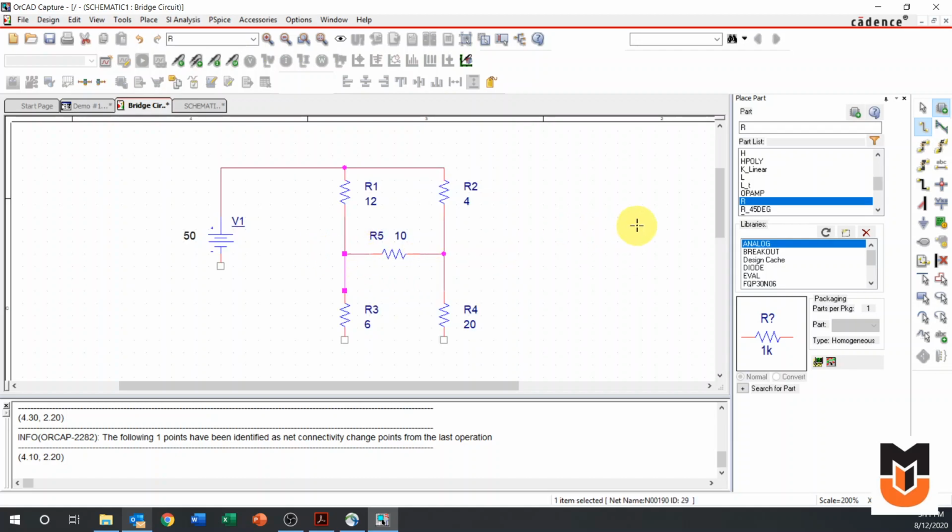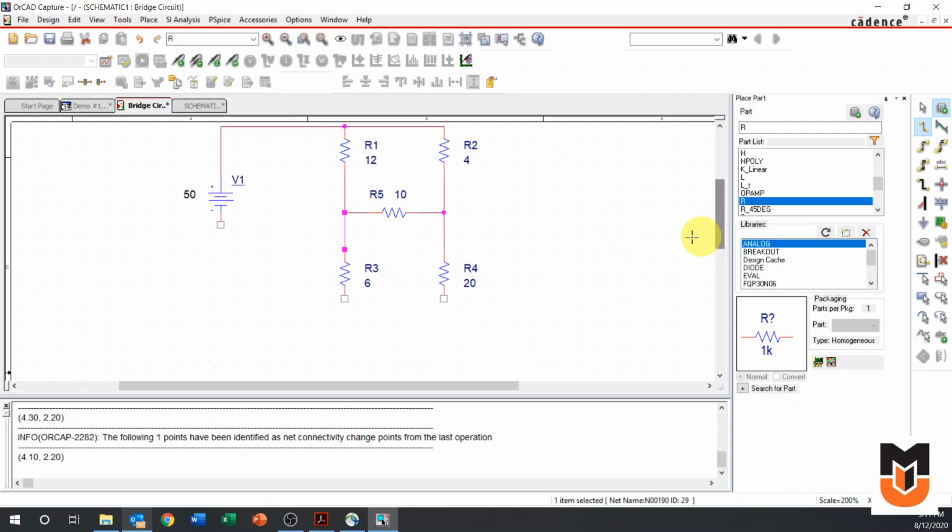So let's say maybe for whatever reason, I'm just going to scroll down a hair here. For whatever reason, I don't want this wire to come straight over and up. Maybe I want to give myself a little more space and go down. So I can first come down with my wire, and then I can left click to set my bend point as being right there, and it won't auto adjust it. And then it's going to auto adjust as I come up here. So let's say I also want to connect this here. And so that would be our bridge circuit.